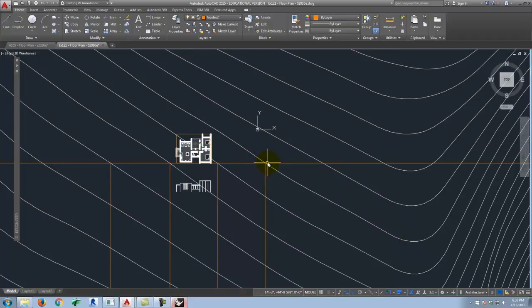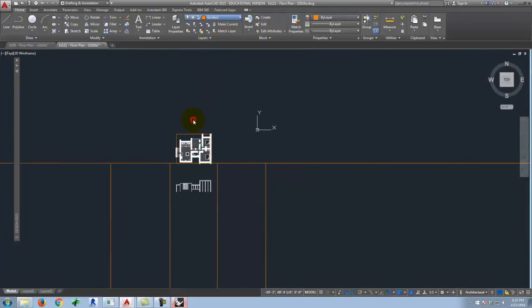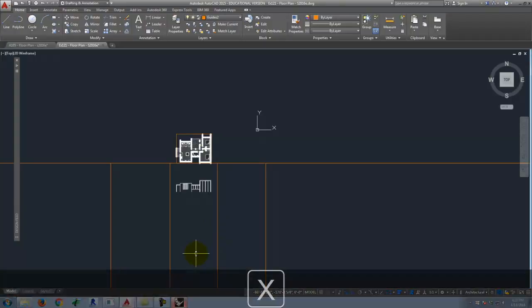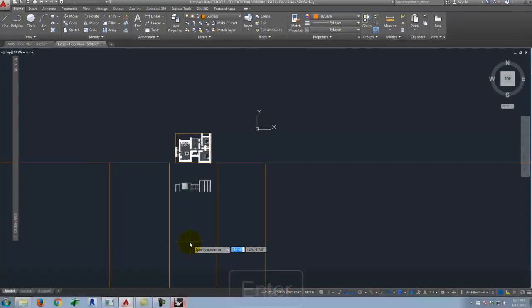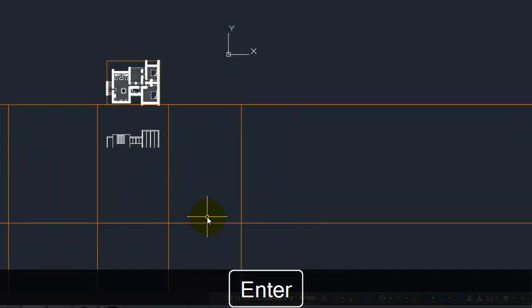Okay, so now that I have that information, I'm going to come up here and I'm just going to turn off the topography altogether. Right? And I'm doing that on purpose because I don't want you to get confused with the topography lines anymore. So I've identified where the topo lines hit at each of these points that is collinear or in the same plane as my elevation. So now I'll start with a construction line, so an X line, somewhere down below my elevation. And it doesn't really matter where. And we'll draw it there.